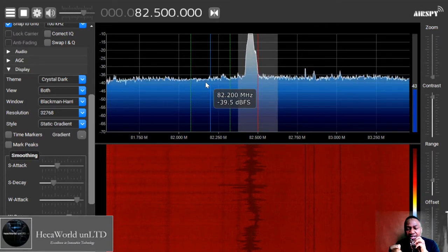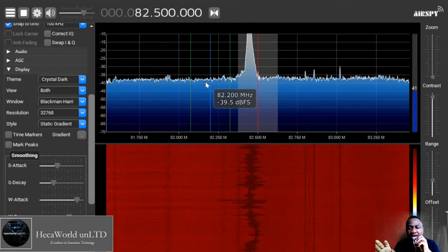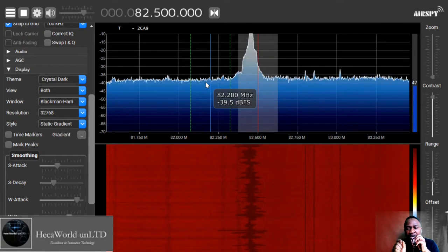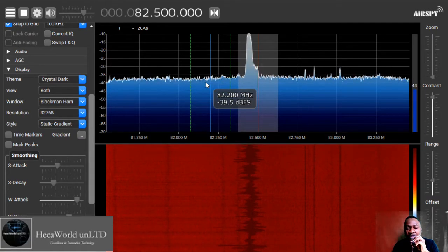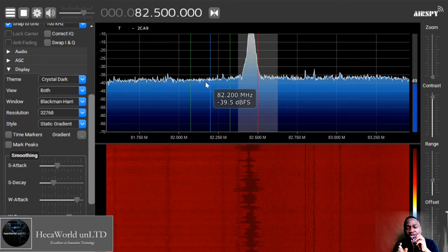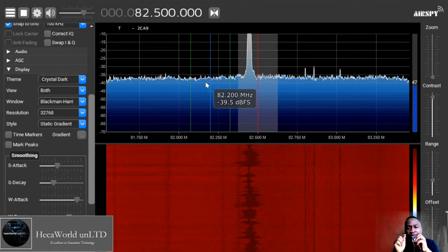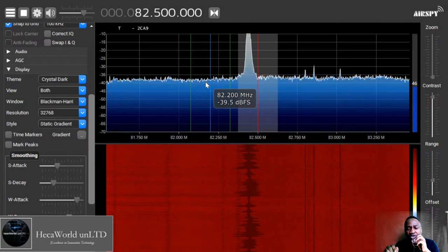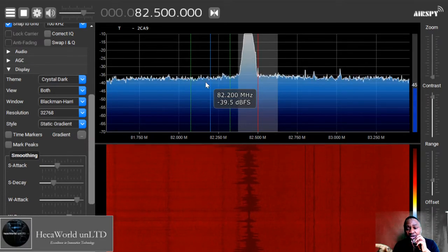The tighter it is, the lower the frequency. The wider it is, the higher the frequency. It just goes in that linear order. Tighter, lower frequency; wider, higher frequency. Then when you have that combination using that tank circuit, L and C, using the formula F equals 1 over 2 pi square root of LC.